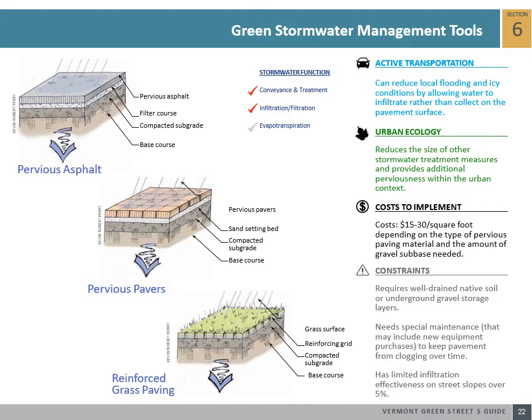Stormwater planters are good candidates for main streets due to flexibility with siting and shape and a small footprint. They can fit between driveway curb cuts, utilities, trees, and street furnishings commonly found along urban streets. Planters can be a very good choice for streets that require on-street parking, but thoughtful design must accommodate pedestrian circulation.